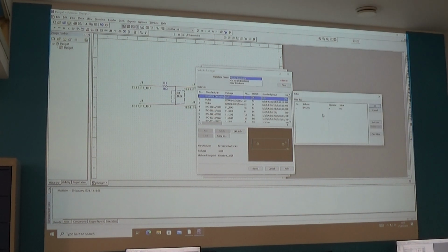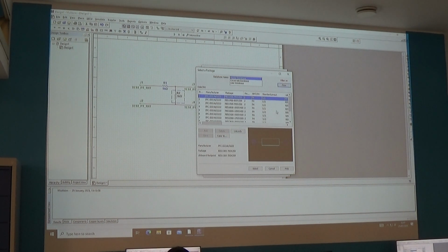Let's turn another filter on. I can tell by the way it's gone quiet. This is the bit people didn't get. So in here I can add a row now, and what I want here is package, because that's the column which has got the description in. I don't want equals, I want contains, and I want the word res, the resistor. I OK it, and you notice that all I have here now is the resistors. Yeah? Wonderful, wonderful. So 2 filters.